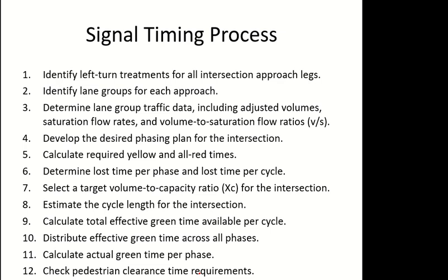Okay, so normally, if the left turning is permitted and we feel it will be too dangerous, we keep it with the straight then. So step one is basically whether you want a separate phase for left turning or you want to keep it with the straight one.